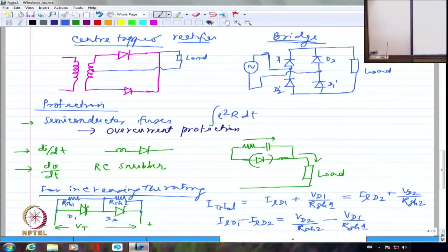Maybe I should have shown this here. I think that's where the problem lies. This should have been shown here. Then I think things are better, because the inductance current now also is not abruptly removed. Sorry about this mistake. I should have definitely shown this here. What you ask is right, because the inductance is in series with the diode. Nothing is averting it from getting the brunt of L di by dt. Right. So this connection should have come here before, like between the inductance and the diode. It can't come after the inductance.